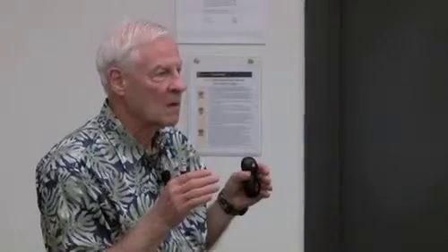So if the flow is steady, if the flame is steady, we did some work at high pressure flames at about 50 atmospheres, steady, just sitting there. We wanted to measure NO, or we wanted to develop techniques for imaging NO. We had the knowledge of the NO spectrum. We would pick a wavelength we wanted to excite. We had line-shaped models, so we kind of knew what we were exciting.